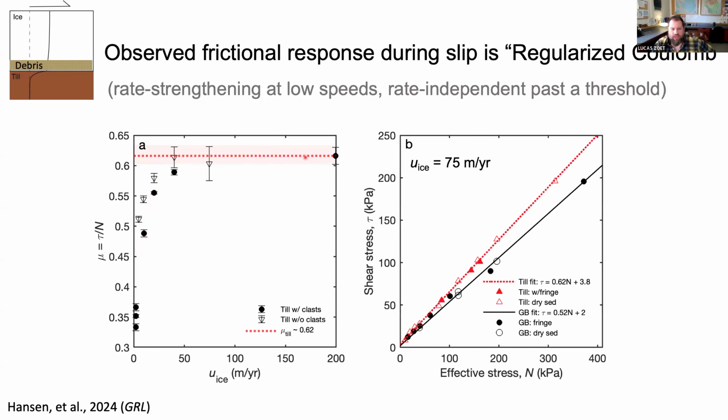Now, once we were in this regime, once we were living in this space, we tested it a little further. This plot is effective stress, which you can think of as how much we're compressing the system, versus the measured shear stress, how much resistance the bed is providing. What we find is as we compress the system harder and harder, the resistance to shear goes up linearly, which is a hallmark sign that the bed is behaving like a Coulomb material. So we're pretty convinced that once you're in this area, it's largely a Coulomb response that's dominating. It's largely this sort of line here.